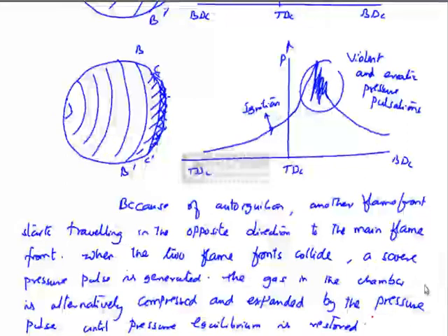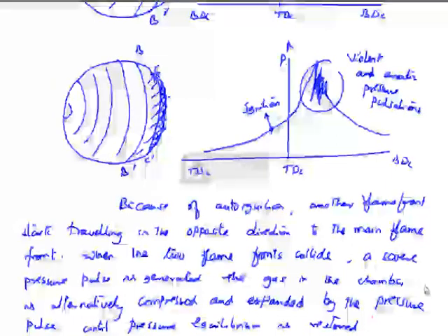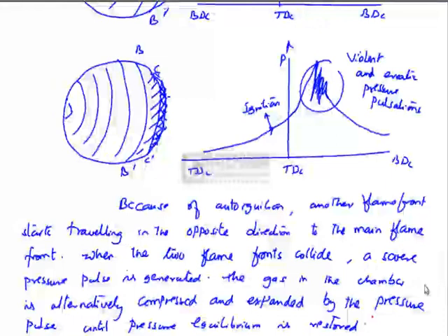This disturbance can force the walls of the combustion chamber to vibrate at the same frequency as the gas. The gas vibration frequency is in the order of 5,000 cycles per second, which is shown in the figure also. The violent erratic pressure variations could lie in the range of 5,000 cycles per second. So the knocking should be avoided at any cost by varying certain factors.